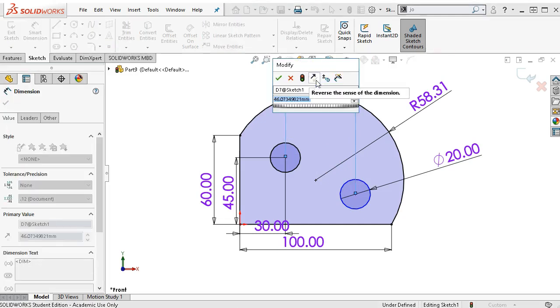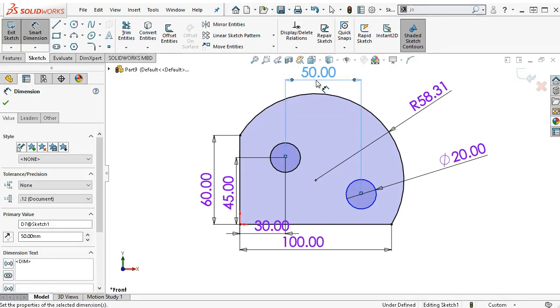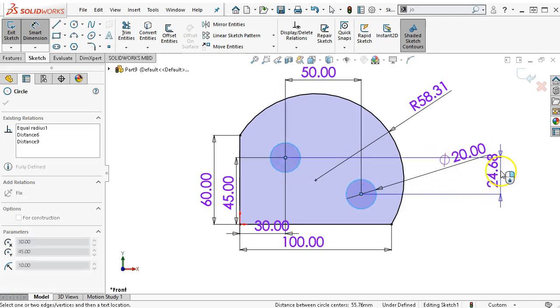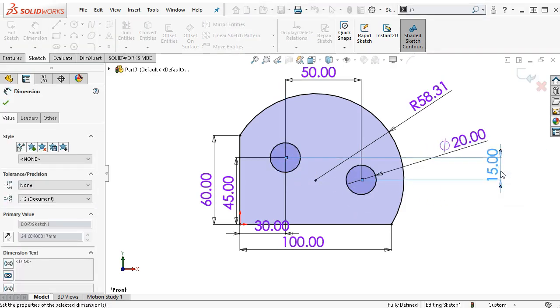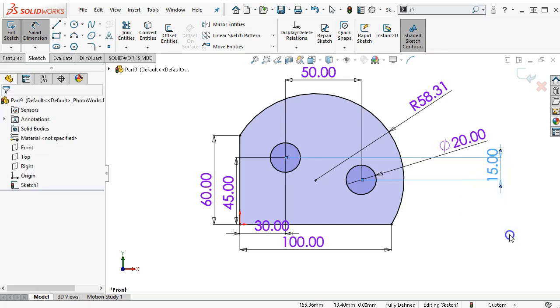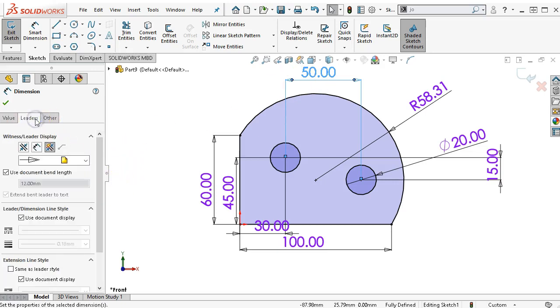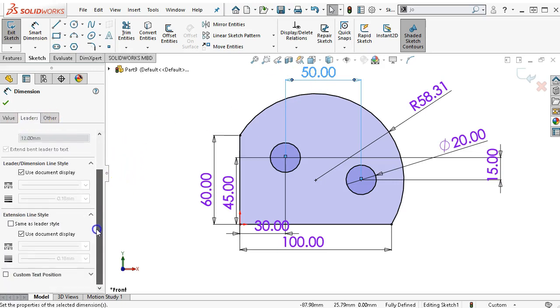I'm not anticipating that I will need to set a max min condition. And between the two, I'm still going to say it's always better to pick the perimeters of the circles than it is the center points. All right, so let's go back and check. I come over to the 50 millimeters. I look at its leaders. We scroll down. There's no arc condition between the circles.